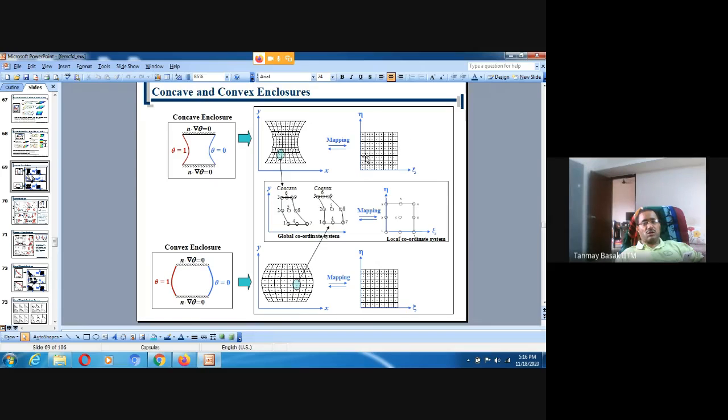We generate all the nodes, and when we map it back, automatically we get the curves. That's the beauty of our mapping configuration and the mesh structure. So this is the regular element. These are the local nodes, and this kind of distorted element can also be mapped to the square domain for numerical integration purposes.